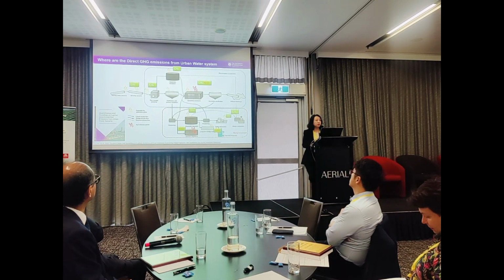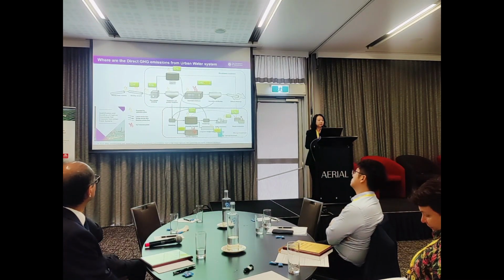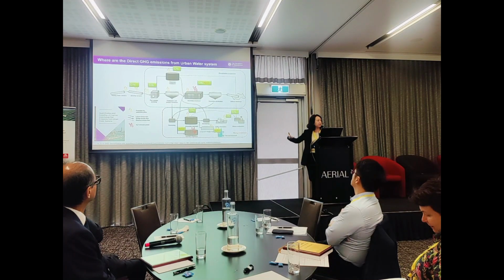Some utilities try to burn all the sludge, or even use gasification, and those thermal cycles may also generate nitrous oxide. Compared with N2O, methane is emitted almost everywhere here. This is because during transportation, a lot of COD is already converted into methane, which may be emitted during transportation. And the rest of the dissolved methane will be emitted as long as there is gas-liquid transfer.